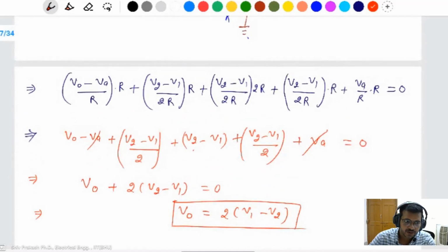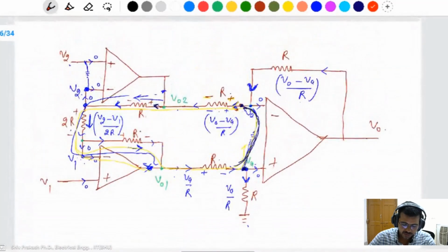Okay, everyone. This question. First of all, take op-amp and find the feedback. Which one is the positive feedback or negative feedback? If there is a negative feedback, then take a virtual short. Then positive terminal voltage is same as the negative terminal voltage. And after that, calculate the current of all of resistance flowing through resistance. Then apply a KVL. Simple voltage Kirchhoff law equal to 0. We will get the answer.